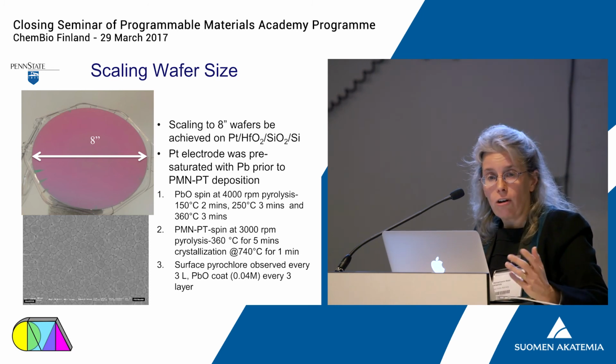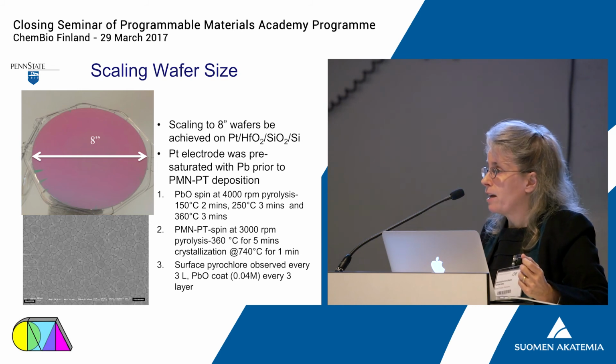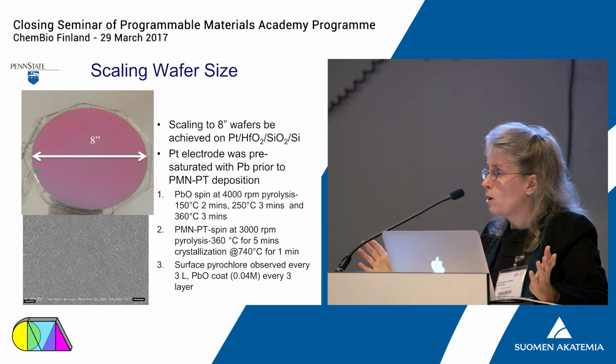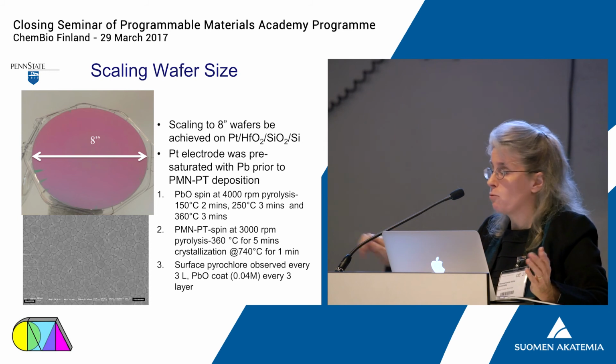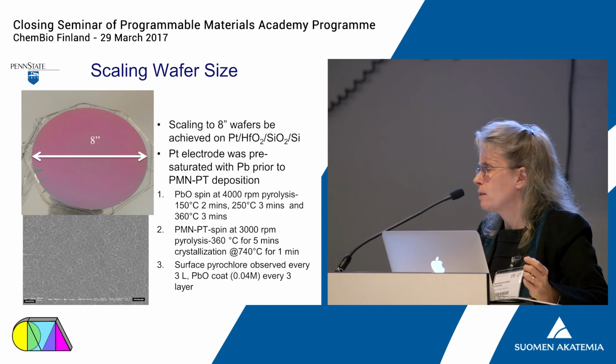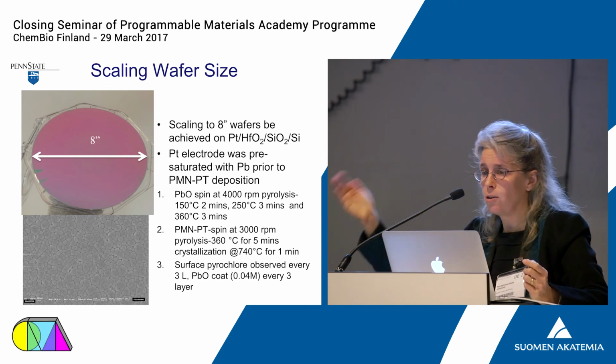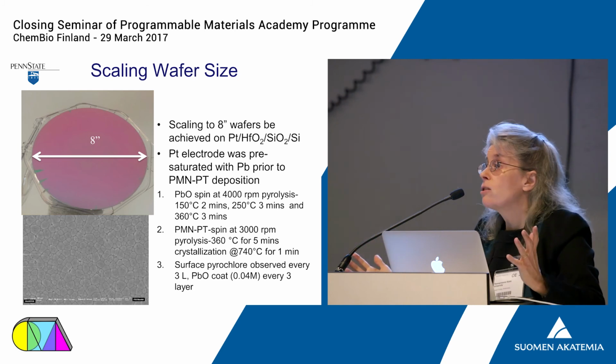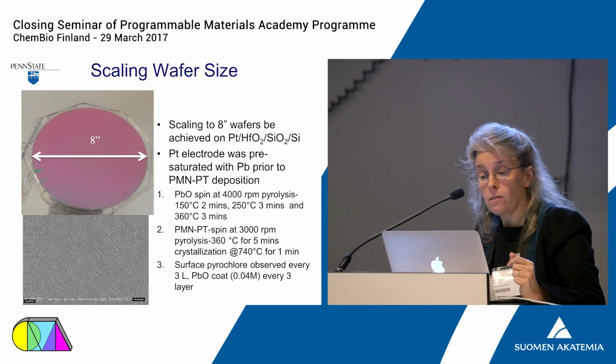And unfortunately, with all lead-based materials, you pop the top on the vacuum chamber, and it takes like 10 runs in order to get the sputter rates consistent, and you have to pop the top for every wafer. So no dice. We actually developed a chemical solution deposition route to do this, which is not how you would do it in industry, but it allowed us to actually make prototype devices.